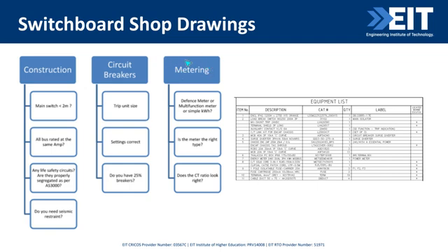And if we're looking about energy metering, you might have a specific type of meter you're after. Maybe you want kilowatt hour meters, or maybe you want a multifunction meter. So you want to check in that equipment list, like what's shown here, that it is correct. So your meter type, perhaps your surge diverter, your circuit breaker, you check the actual catalog numbers to make sure they're correct.